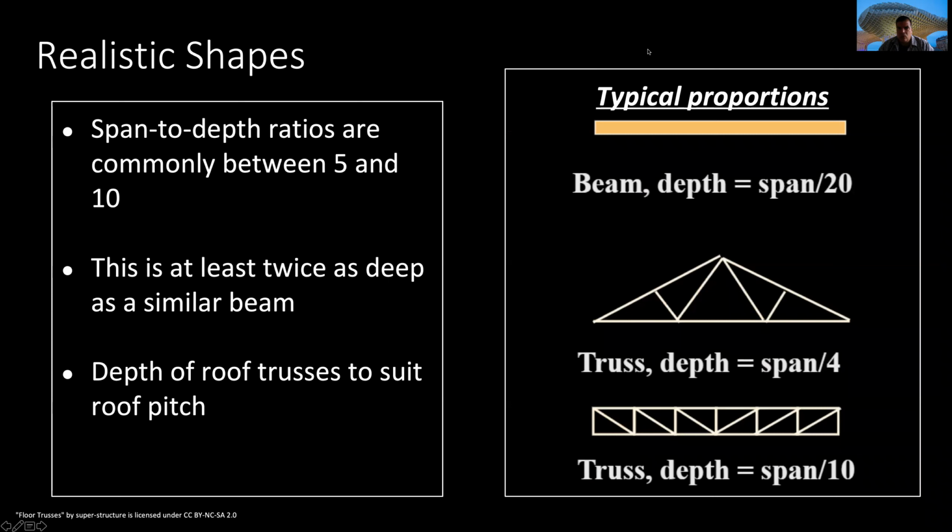I mean, if you are doing a concrete beam and you are doing a section in your design classes, you need to understand that if this beam has a span of 10, when you do the section of this beam, the height or depth of the beam could be 1 to 10. With some types of wood, with steel, it can be 1 to 20.